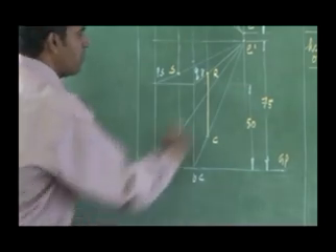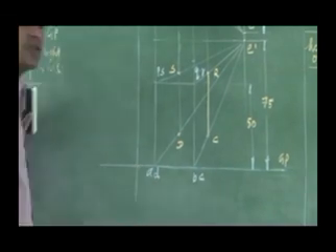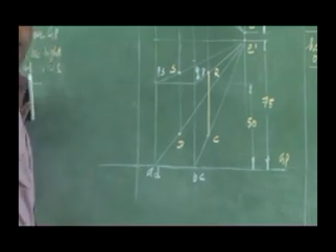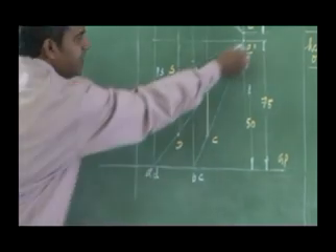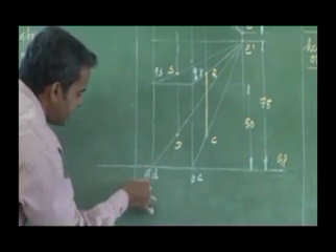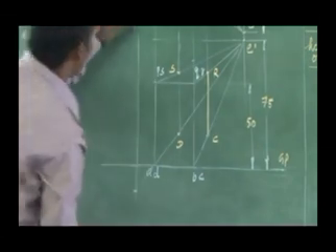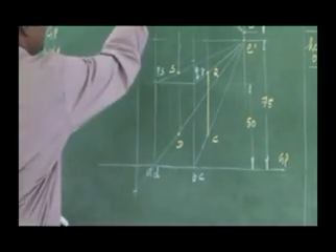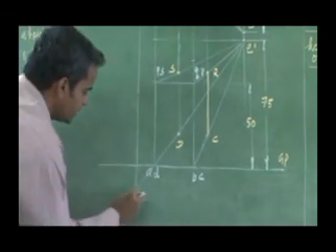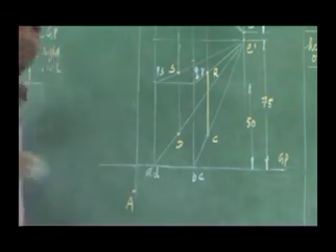So the visual ray line of A ends up to here. What do I have to do to get the perspective location of A? I have projected the AP intercept. Just extend the visual ray line of your front view, in the same manner, to where it meets the corresponding intercept projector. That location is going to be my perspective location of A.